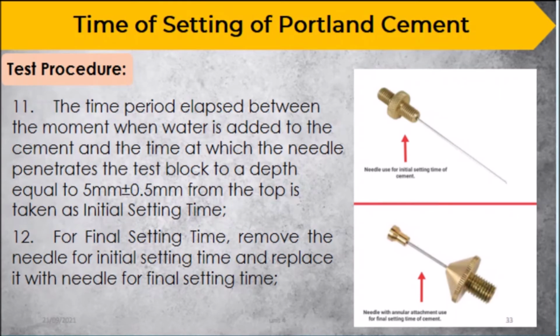The time elapsed between the moment when water is added to the cement and the time at which the needle penetrates the test block to a depth equal to 5 mm plus or minus 0.5 mm from the top is taken as the initial setting time.